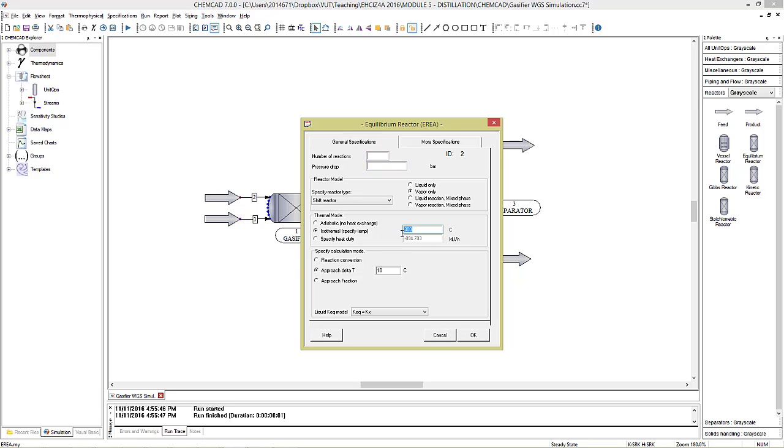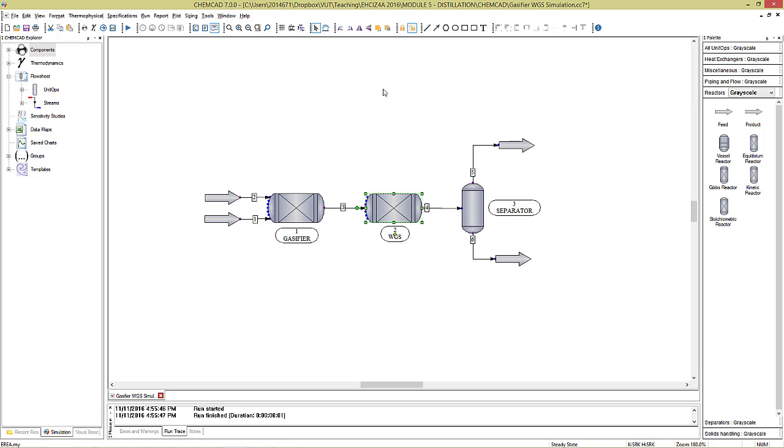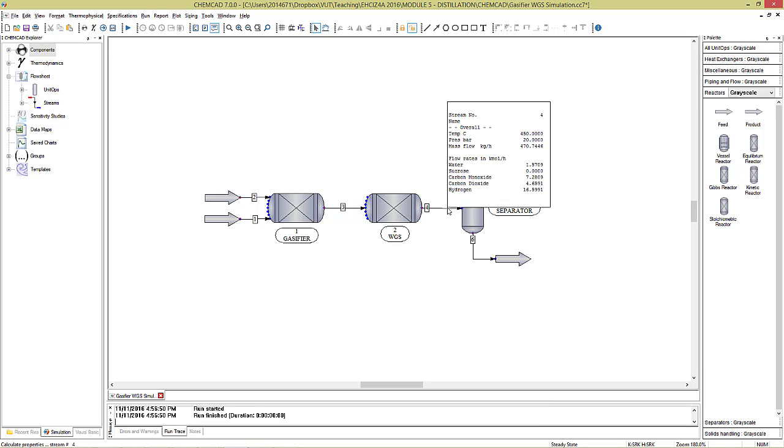I would say let's go to 450. I would usually go higher so that I pass the required point and then select maybe a point in between, but at this point I will just go sequential and say let me go 450, and then let's run this, and then we can look at this. We have increased our carbon monoxide slightly, but our hydrogen is still the ratio is supposed to be, if you look at it, 7.3, maybe supposed to be 14.6 for hydrogen to be right on the molar ratio of 2 H2 to C ratio. So we still need to ramp up the temperature a little bit.